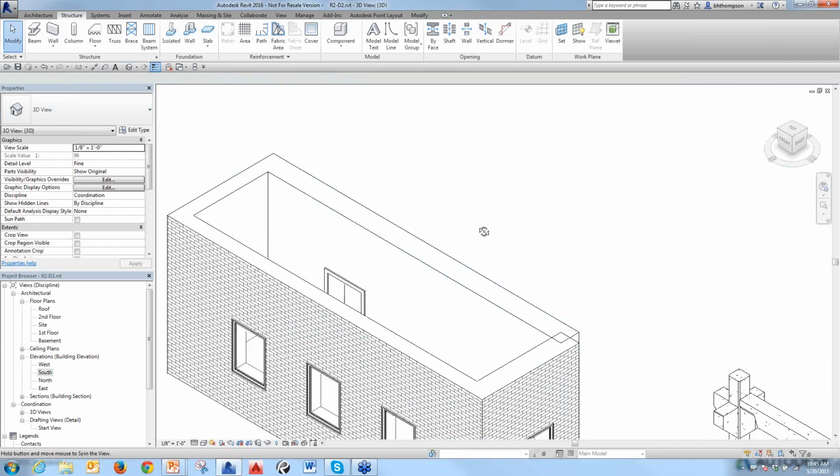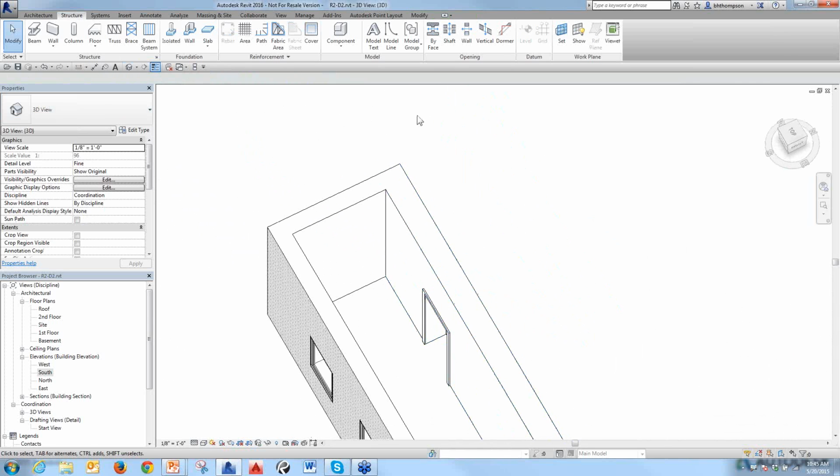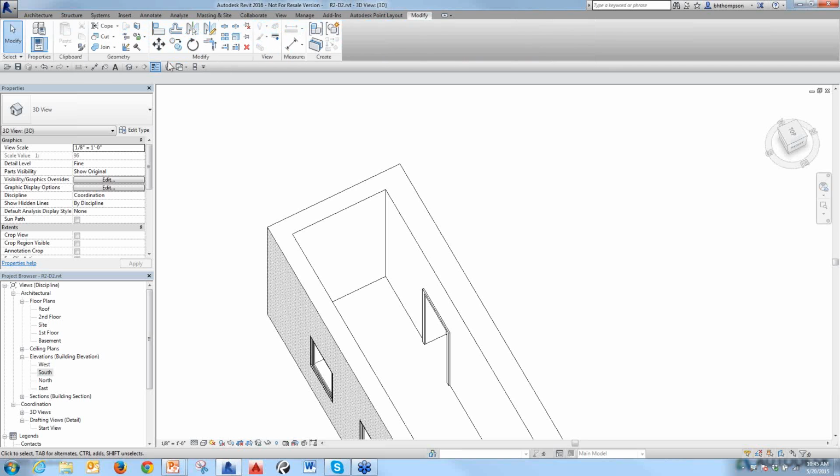No, I have one in here that I thought was kind of cool because everybody misses this, the joints in here. So they did do another one. It wasn't in the deck, but if we go to the Modify tab and come over to the wall joints, you now have allow or disallow the joints, which is pretty cool. So now they separated that. You no longer have to go find that magical dot and remember to right click on it. You now can do this all within the wall joints and clear that out.